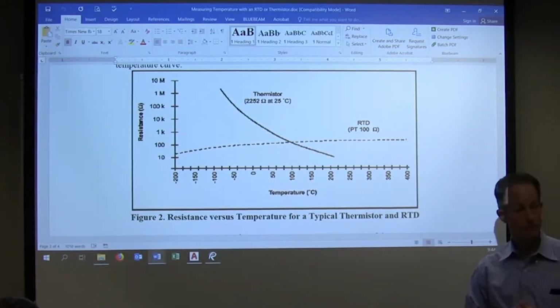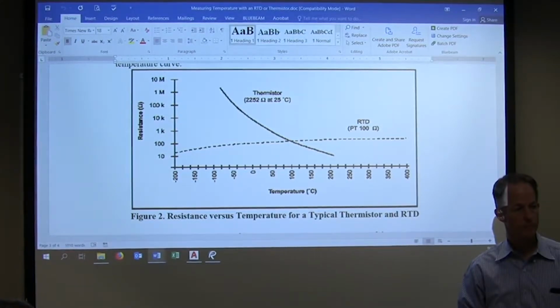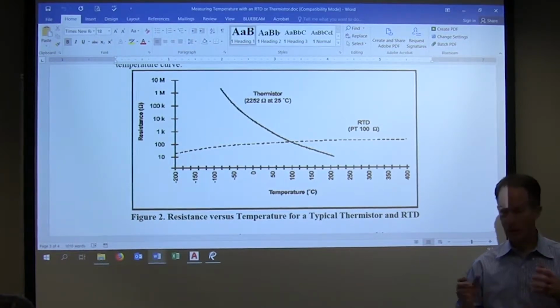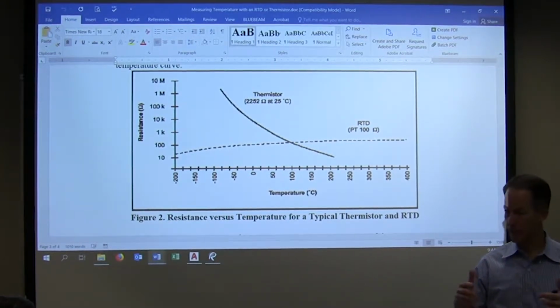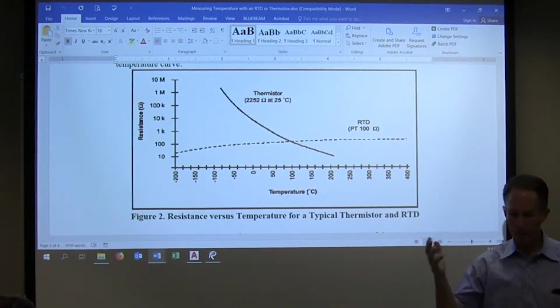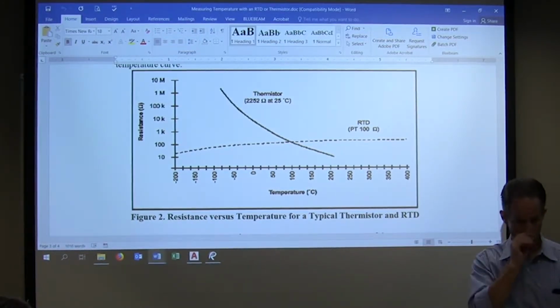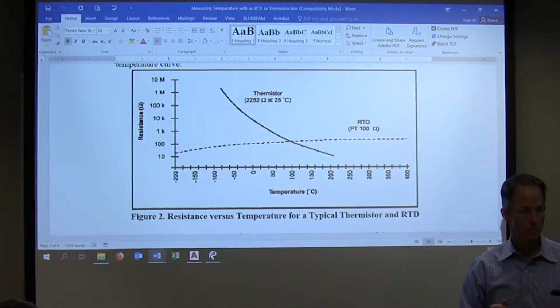The RTDs we use a lot because of our high temperature requirements, so the ambient temperature these probably wouldn't tolerate. And that's another thing, certain sensors can work in certain temperature ranges, right? So there's certain RTDs that you're not going to run on high temp stuff because they haven't been built to withstand 400 degrees. That's too hot. It'll melt the solder joints or whatever they've got in the sensor, it'll all come apart. Yeah, and then the really high accuracy ones are matched RTDs at the factory, and then those, I think we're talking hundreds of bucks.